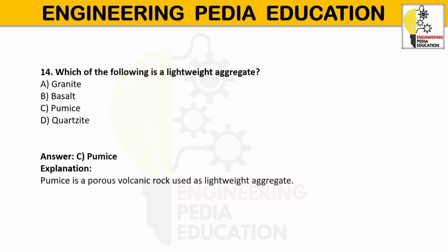Pumice is a light-colored, highly porous volcanic rock: lightweight, highly porous, rough texture, low density, brittle in nature. Used as lightweight aggregate, low density concrete blocks are made with it, used in insulating material, and sometimes used in abrasive cleaning products.